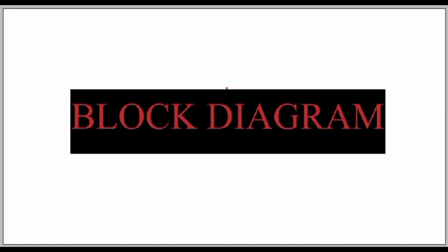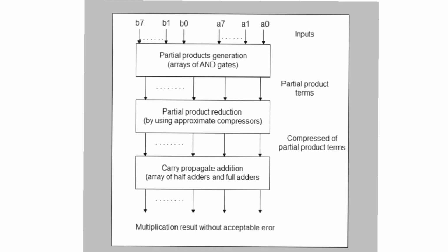I have learned about analog VLSI, digital VLSI and ASIC design in my VLSI domain. The project mainly emerged from the ASIC implementation through the ASIC flow and ASIC design. It is about a multiplier. Coming to the block diagram, first I will give a brief description of the multiplier. Multipliers are fundamental subsystems of microprocessors and digital signal processors. A multiplier includes a few blocks like partial product generation, partial product reduction, and carry propagate addition.